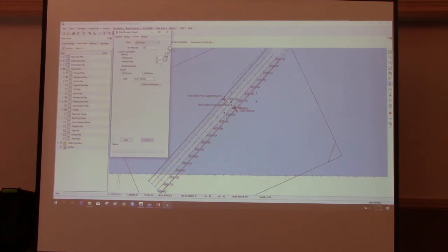Okay. Then if you go to the contour menu, yeah, we'll leave it at 2D. Tin max size, since these are probably longer lines, leave like a 500 or something foot tin max size. These lines are pretty far apart. I can do my smoothing options here. I use the color scheme. Then I have my contour attributes.